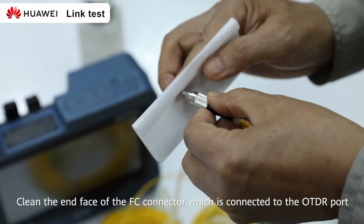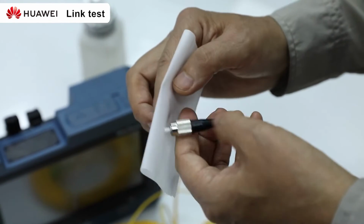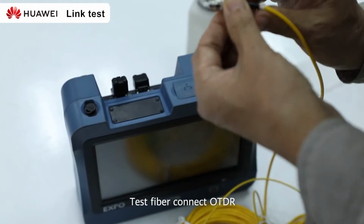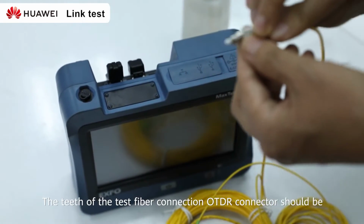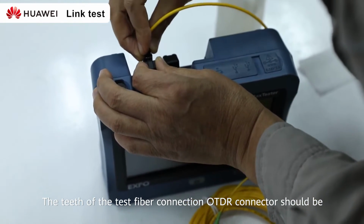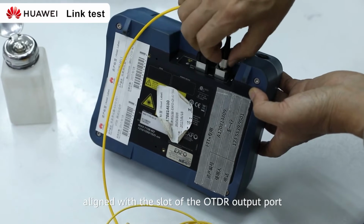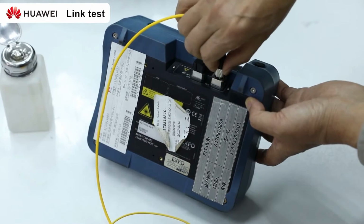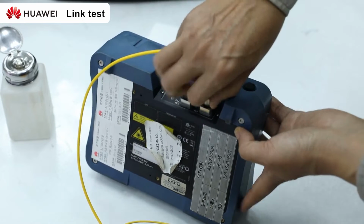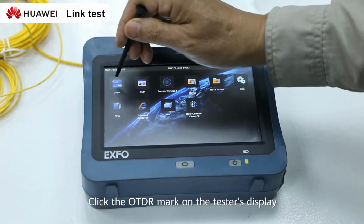Clean the end of the FC connector, which is connected to the OTDR port. Connect the test fiber to the OTDR. The teeth of the test fiber connector should be aligned with the slot of the OTDR output port. Fasten the cables after they are properly installed. Click the OTDR mark on the tester's display.